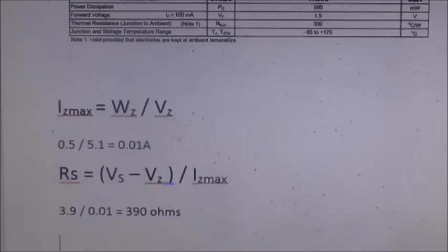However, if I'm only supplying a reference voltage, a current like that won't matter. All I'm going to be doing is feeding the voltage to a microcontroller, which doesn't need much at all to set it off. So we can be happy with that, and we can put the 470 ohm resistor in there and get a 5.1 volt output, just as we saw.